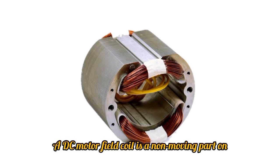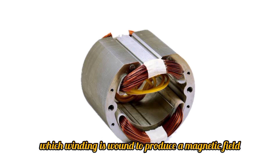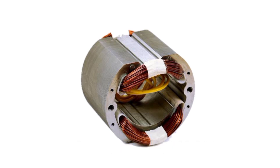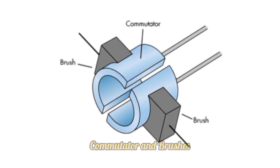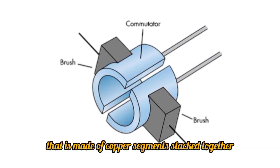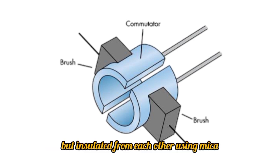Field coil or stator. A DC motor field coil is a non-moving part on which winding is wound to produce a magnetic field. This electromagnet has a cylindrical cavity between its poles. Commutator and brushes. Commutator. The commutator of a DC motor is a cylindrical structure that is made of copper segments stacked together but insulated from each other using mica.